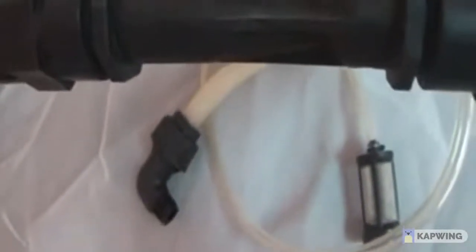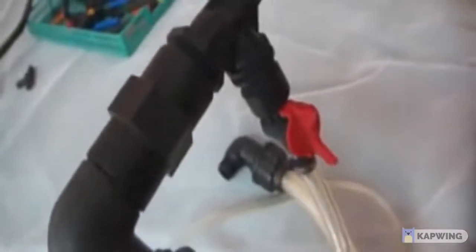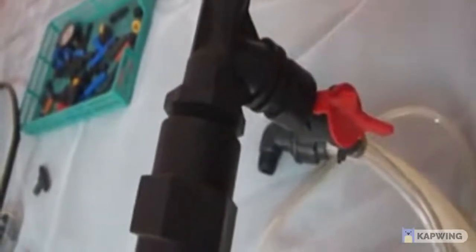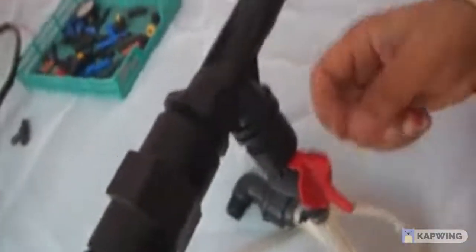So one end is your inlet end, another one is the outlet end, and this is the part where the diameter of the pipeline has been reduced. So the area of flow is reduced, and that is causing the change in the velocity, and thereby it is creating the negative pressure, and with the suction the fertilizer which is kept in the tank is being injected into the system.